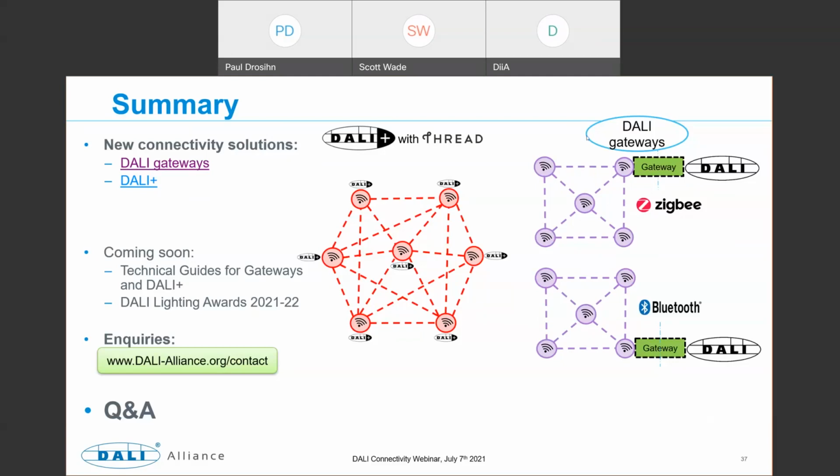An interface is an informal term just now. If someone is creating a device that does this but to KNX or to RS-232 or RS-485, we don't have a standard specification for that. So it's best not to use the term gateway just now for those until we have a standard specification that tells you how to convert or transport or control from that system to the DALI system.